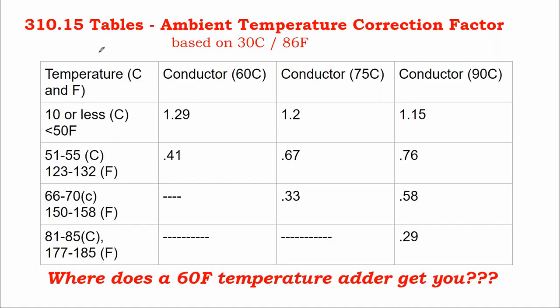We were talking about the temperature correction factor tables in the National Electric Code, and we learned that one of the most important things is to read the actual heading, because in the heading there's a qualifier to this chart at a certain temperature range. As we'll see in just a bit, this same chart will appear multiple times in code.